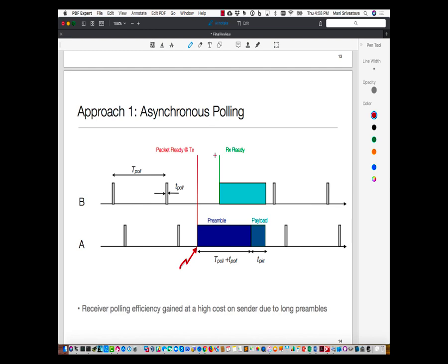This wake-up time could be pretty tiny, whereas the packet transmission time may need to be long enough. But the other challenge also is that in many settings, you want to keep radio silence. Military networks and all, they don't want unnecessary transmissions going out because that means the enemy can hear it and then jam or attack or whatever. So that's the penalty in the other case.